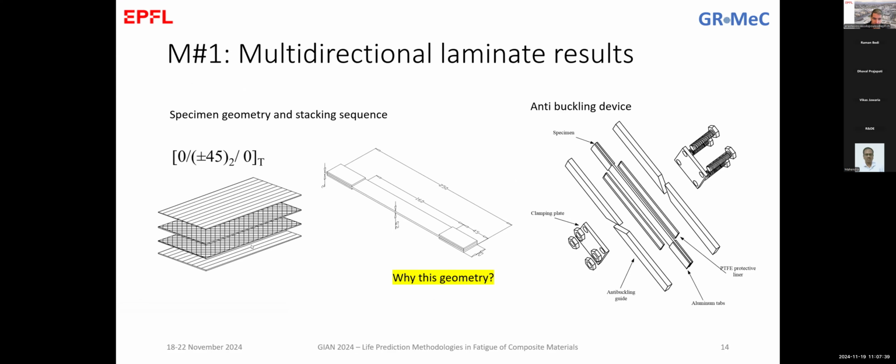My 0 has 2 UD layers and 2 layers of plus minus 45 degrees. And this is why I said that this is a discussion that we did yesterday, that we almost never, if I can say it like that, tend to use unidirectional composites with one fiber direction for structures, exactly to avoid these problems that you're mentioning. We try to homogenize the material a bit, to mix layers, so that we can consider effects that are not actually seen during the design.